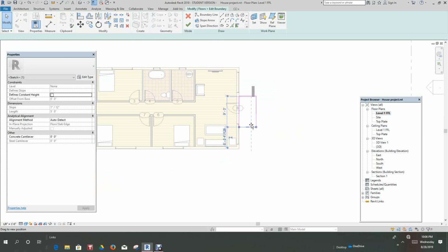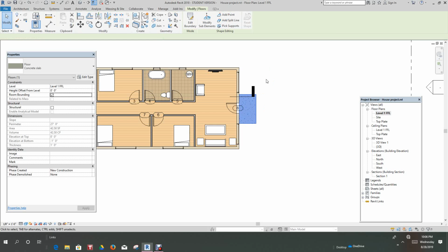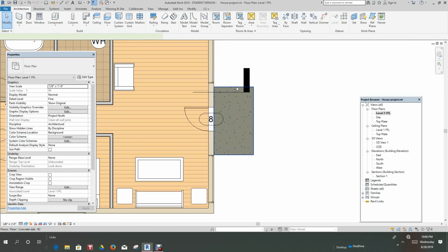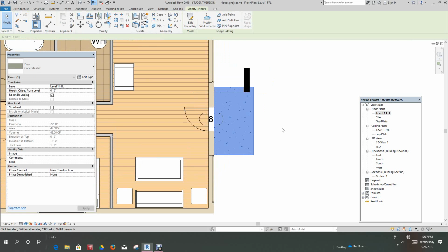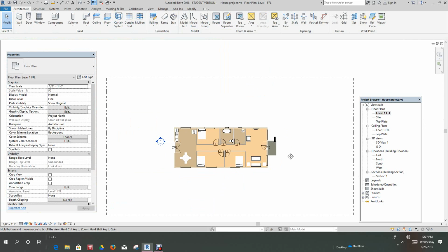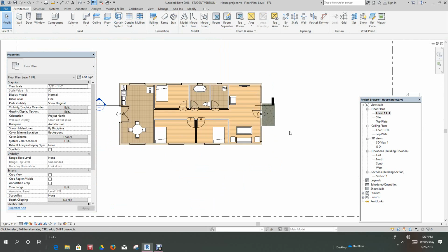Now you can put on any surface you want, if you like, by using the paint modify tool. Let's do it that way. You can do anything you want here. So this should be about the same height as the floor slab in the house. Now I probably want to knock it down a couple of inches so the water doesn't go into the house. That's just something you want to do if you like. I'm going to keep it at 0 just to keep things simple here.